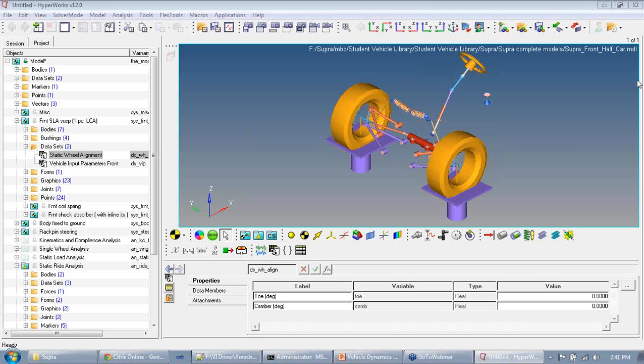And after that, what you should do is, on the top of the browser, there'll be a line called model. Right click it and then say apply attachment candidates. This will throw up a pop-up, or may not. If it does, click on auto resolve attachments and close this. What this does is it sets up the template for you.